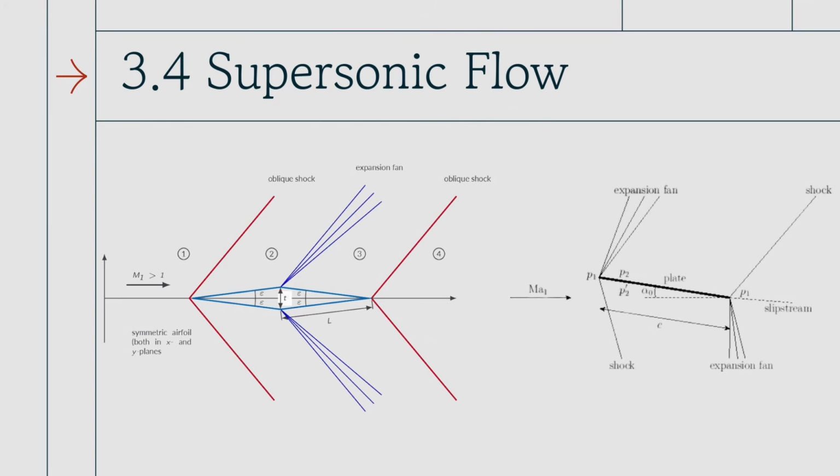It's not super obvious, because there's no wall on the other side, but you can imagine the flow is being constricted into a slightly smaller area. That's why you get a shock there. But then once you reach the middle of the airfoil, and now the airfoil is slanted the other way, you are essentially expanding the flow, even though it's not super obvious.